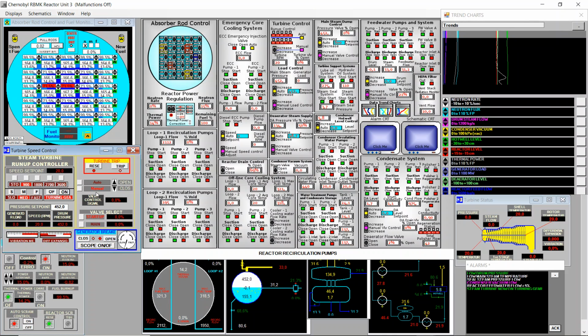In this tutorial we will use the manual setting. It's here in the turbine speed control. In the previous one, it doesn't matter if you didn't watch, I will tell you now what I did. I used the auto setting. What this setting does is cycle through these RPM values one by one at a constant speed. So you select either slow, medium or fast speed depending on the temperature at the beginning of the startup, and it ends up at 3600, and then you synchronize the turbine.